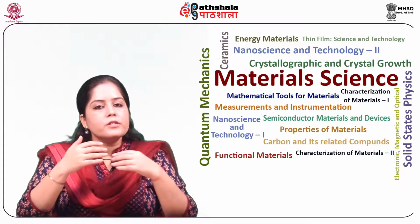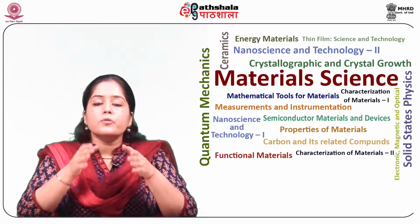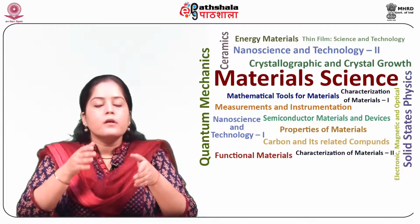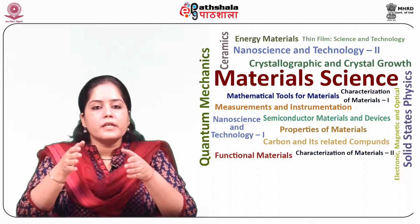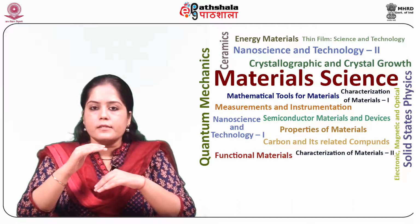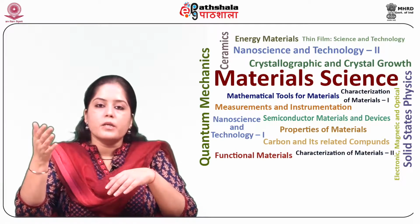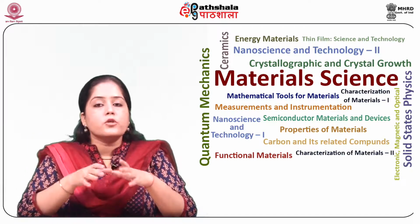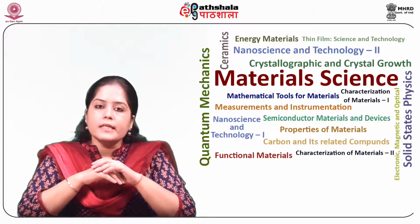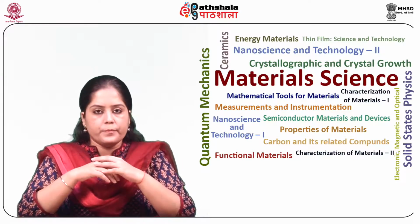Since there are frequent transitions between the two valleys, in order to maintain the equilibrium, early theories of the Gunn effect assumed that the electrons in the two valleys are in thermal equilibrium at some higher temperature, the electron temperature, that is Te, corresponding to their increased energy.